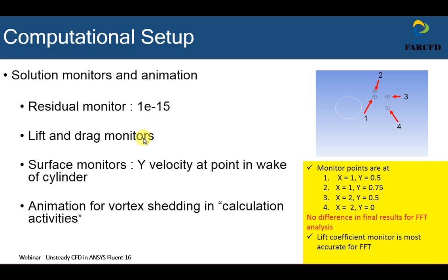Lift and drag monitors are used to record the drag and lift coefficients. Surface monitors are created to record the y velocity at the points shown in the figure. For part 2 of this webinar we will only show you surface monitor point 1, but we encourage you to create all 4 points and corresponding surface monitors.